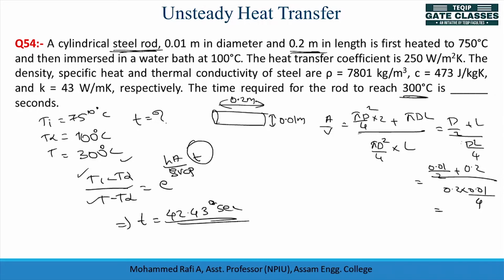Okay, so guys, please don't get confused about how we are considering the length. If the length and diameter are comparable, then you have to consider the end face also. If it is an infinitely long cylinder, then you can ignore the end face area, because the area on the end will not be that relevant. If I am adding 100 plus 1, it will be 101, but if I am adding 10,000 plus 1, that difference will be negligible, right? So let's move on to the next slide.